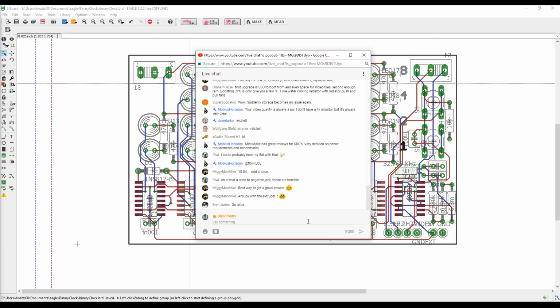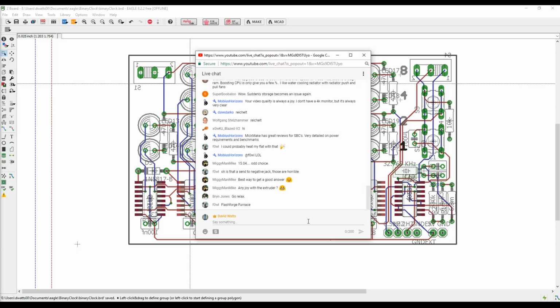That was a disappointing time, but I fixed it by just taking the nozzle out and cleaning it and everything. It was fine. But recently I've been having real issues with the extruded filament not creating proper infill. So the external perimeter layers were fine, sort of. There'd be a lot of stringing, and some, you know, when you get sort of hair bits flying off, there's a lot of that, and I just didn't really understand what was going on, and there were lots of potential causes. And the extruder drive would click, so it meant that it was sticking. I understood what the noise was, but I didn't really understand the cause.